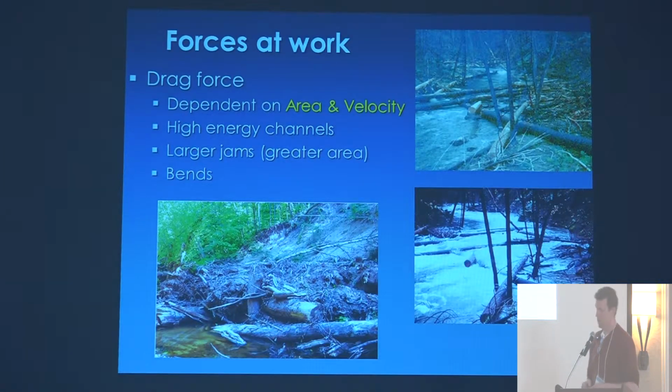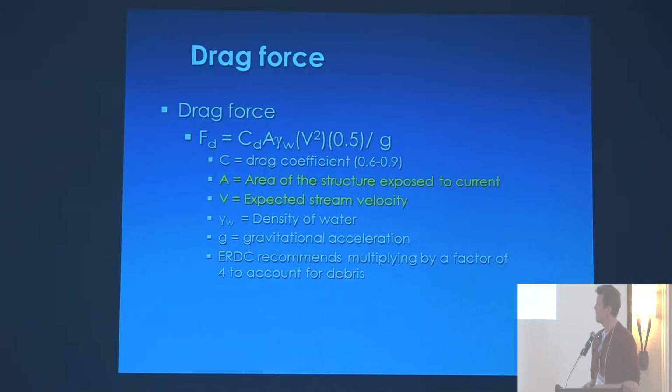So what are the forces at work? Drag force and buoyant force are the primary forces that we're concerned about. Drag force is essentially dependent on area and velocity. You can start out with a wood complex that has a certain amount of area to it, but you have to watch that area change over time because wood collects other wood. So your drag force in the beginning of the project might be different than it is a couple of years later. And then, of course, it's higher around bends and steep areas where you might have greater velocities. Boring math.